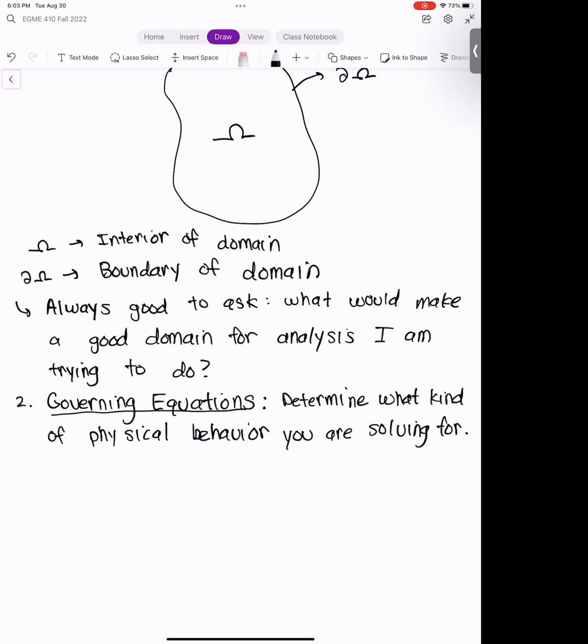And so there are a lot of other options from that list as well. So there was a static fluid simulation, a static thermal simulation, dynamic simulation, modal simulation, right? And so by choosing the type of physics that you're solving for in ANSYS, you're implicitly choosing what governing equation you're solving, okay? And again, this might seem obvious, but it's something that you have to think about. What are the relevant physics? What are the relevant things that I'm looking to solve for? Okay?